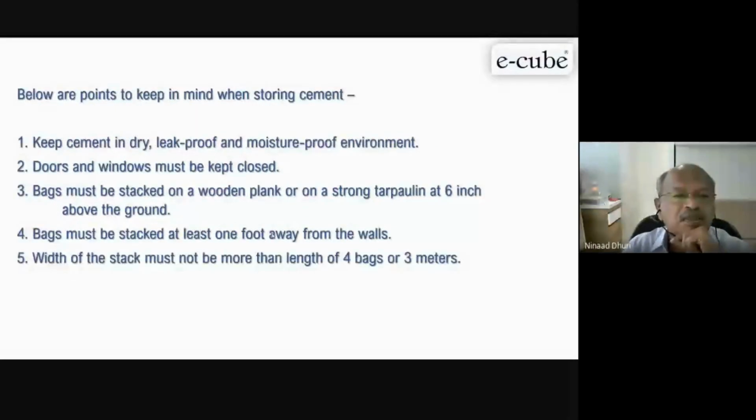So keep cement in a dry place, a leak-proof, moisture-proof environment. Doors and windows must be closed. Bags must be stacked on a wooden plank at least 6 inches from the ground so that they do not attract moisture. Bags must be stacked 1 foot away from the wall, and the width of the stack 3 to 4 meters, not more than that, because you have to have proper movement also.